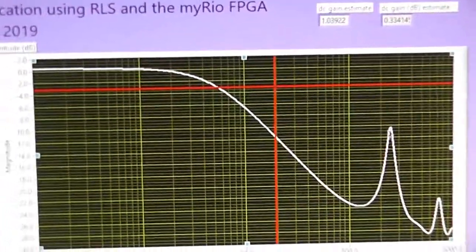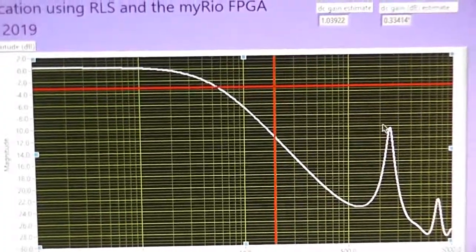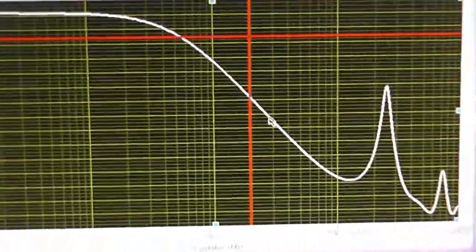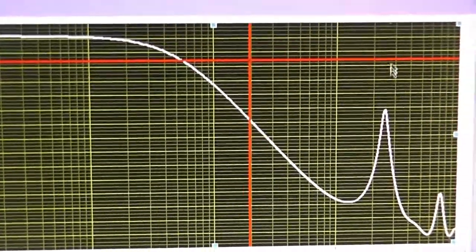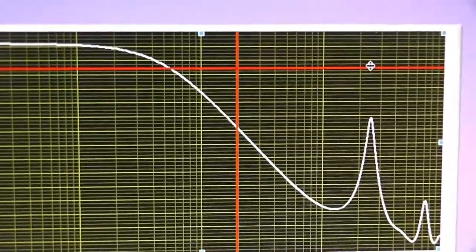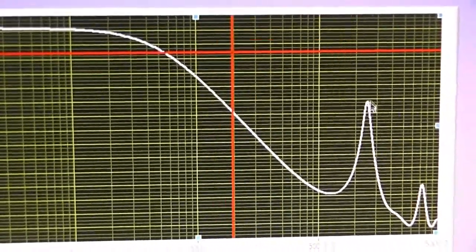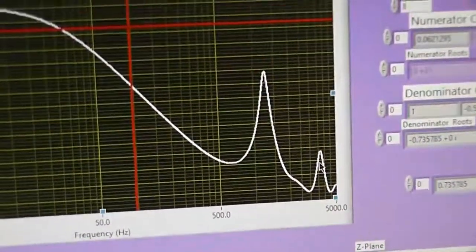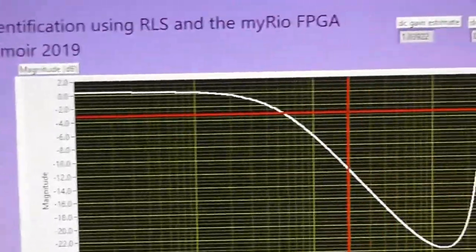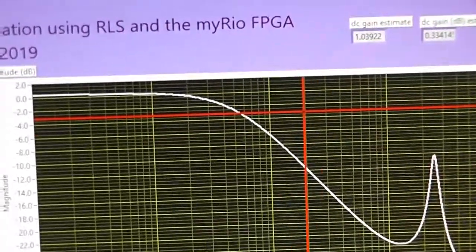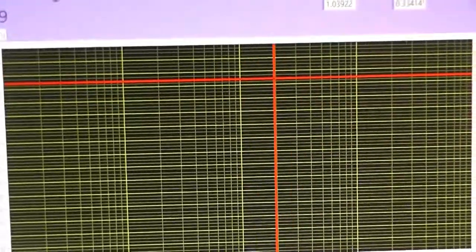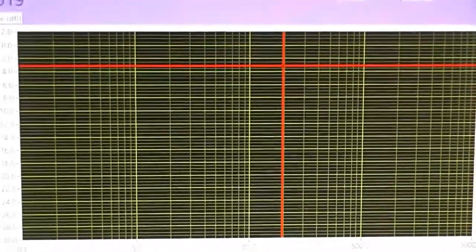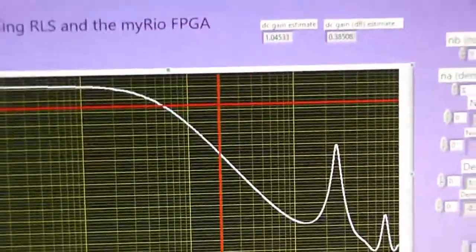Okay, and you can still see that looks pretty dangerous because that's going to poke up through 0 dB. So I've got to be careful how many phase advances I put in, because I'm going to get an oscillation at that frequency. And even if we did something about that, we could try notching it out or something. You've got other ones coming in. I'll just run it one more time to see what we get. Go again. I got much the same again.